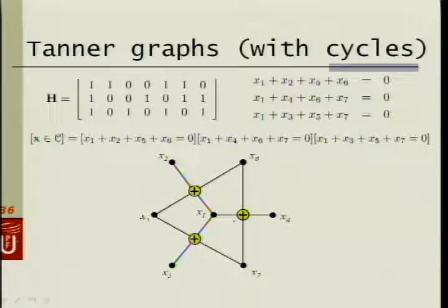Remember that to be able to use an iterative or turbo algorithm efficiently on a factor graph, the loops must be big enough. So we cannot expect to have good convergence properties if we use an iterative algorithm on a code like this, simply because the girth of the graph is very small. To have a code that can be efficiently decoded using an iterative algorithm, we need big loops, and consequently we need a large number of variables. So we need block lengths that are considerably large.